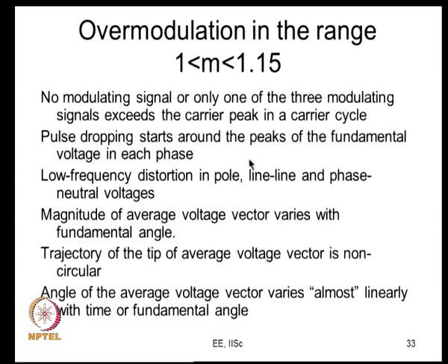And where does it start? It starts around the peaks of the fundamental voltage, that is where the sinusoidal signal goes beyond the carrier. So, the pulse dropping of each phase would start around that, and you will see the pulse dropping now, but the overall pulse dropping duration will be less than 60 degrees in length.